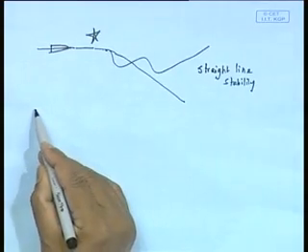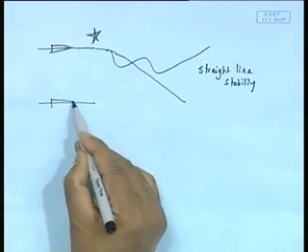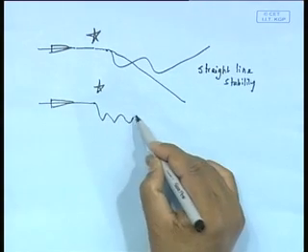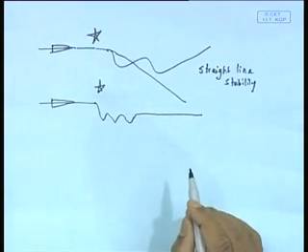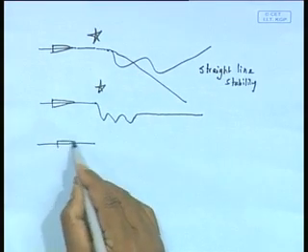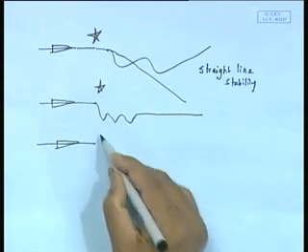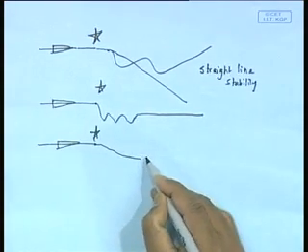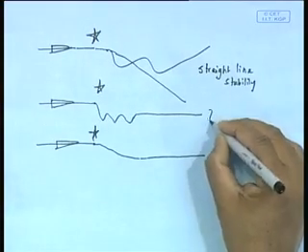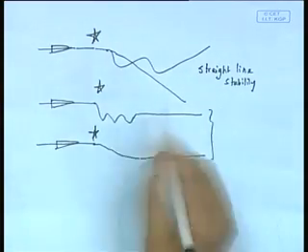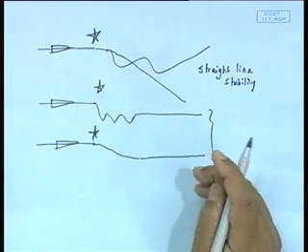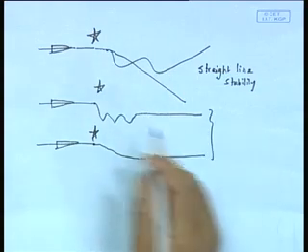Now the second one. My original path is here, I give a disturbance here. The disturbance would have gone something like that, but ultimately again it goes to a straight line. Or it is coming here, I gave a disturbance here, it deflected, but ultimately came to here. If the ship behaves this way, or possesses this characteristic, we call it directionally stable, because the directions are the same.